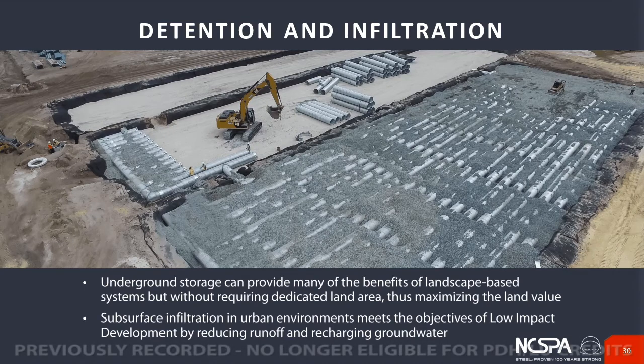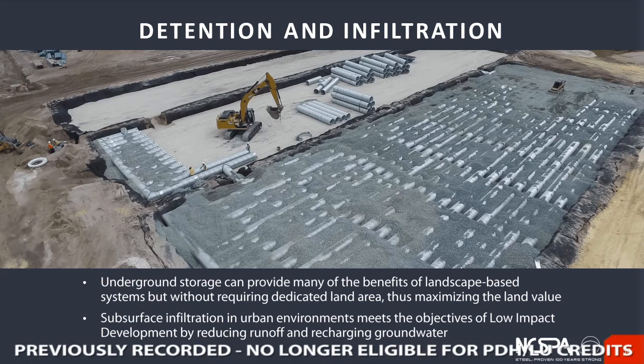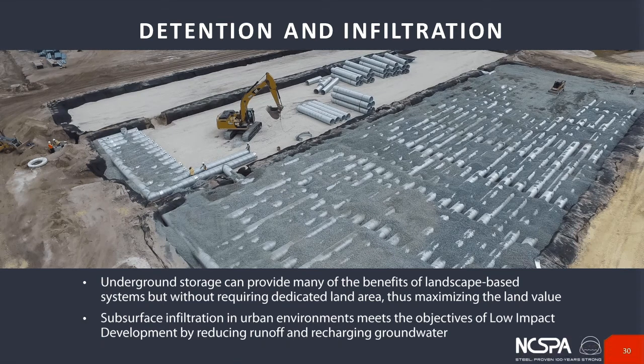And you can either detain the water, or you can also recharge the local soils with the stormwater as well, and use that for storage. Mark will be talking a little bit more about those kinds of systems later on in the presentation. I'm going to focus primarily on detention systems, and you can see here this is a job site that has a pretty extensive system. We'll talk a little bit more as we go along about some of the particular features and benefits of using corrugated steel pipe in these applications.